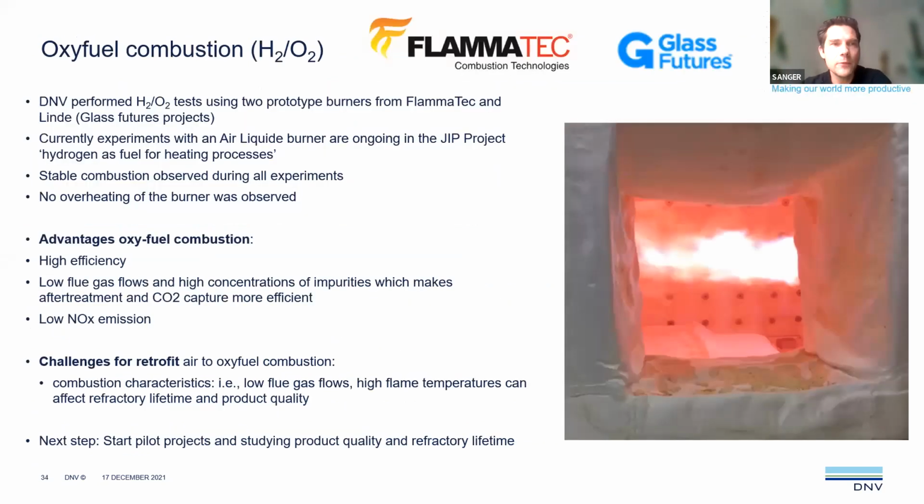Other tests we are currently performing and also did. At the beginning of the year, we did together with Flametech and Lindegas for the Glass Future project, we tested some oxy-fuel flames, as you can see here. So there we used 2 dedicated oxy-fuel burners, and both burners worked very well. So based on that, you also can say, okay, we also can use oxy-fuel combustion, pure hydrogen oxygen combustion, and that might also be beneficial, because if you have electrolysis, then you produce hydrogen and also oxygen, so that will increase your efficiency. So this might also be a solution for the future.